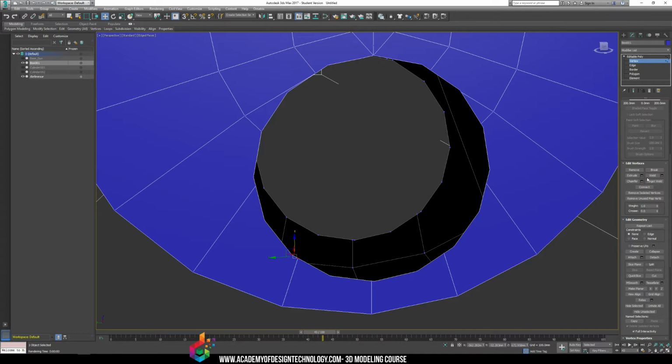So the same thing we did for the top hole in our model. We find vertexes that are really, really close. We can weld those together. Any ones that are hanging out in space a little far away, we can then cut to match the closest edge possible. But try and match any vertices that are just floating in space in nowhere. Try and get them as close as possible to matching other vertexes, and you're going to see a lot cleaner meshes.